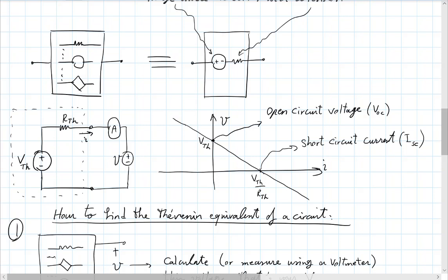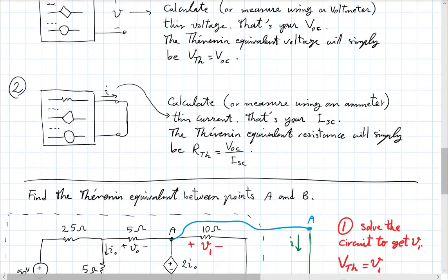Can you try this on your own? So propose what I should put inside the box using a resistor and a current source so that from the outside it looks exactly like this, the same IV characteristics. Any suggestions? How about putting a current source in series with the resistor instead of a voltage source? So I just replace the voltage source with a current source. How about that? Any reason? Well, let's see what a current source in series with a resistor does.